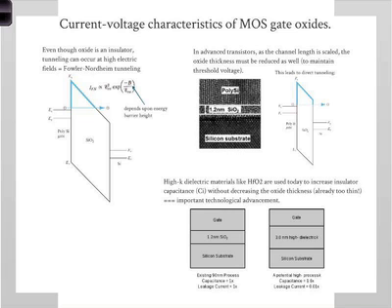Okay, and you add them up by billions of transistors, you get a pretty significant heat loss, which is the reason why your big computers have to have a fan. One of the main reasons, by the way, and the reason that computers get hot. You're losing heat because of this so-called leakage current. And this can happen even when you apply no voltage or very low voltage to the gate.